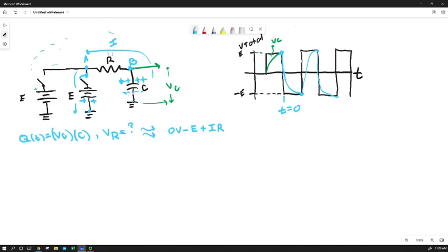So effectively we've got a backwards. This charged capacitor, as shown, is going to act again like another voltage source that's in backwards, minus V sub C. And that's going to equal 0 volts again. So this is our KVL expression.